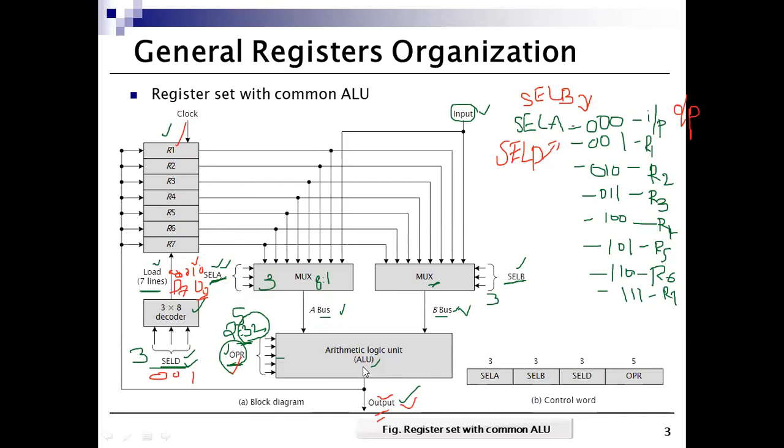What is the stage that it is doing? Execution of your instruction. Fetch and decoding are over. After decoding, we came to know how to perform the operation, what the operation is, where the operands are, and what the destination is. So this control word is needed for this unit to complete the execution stage. This will initiate one of the micro operations.